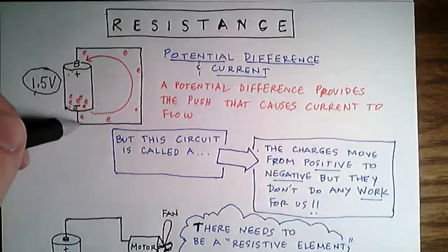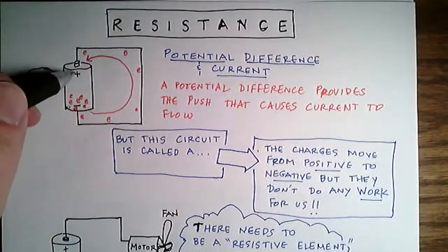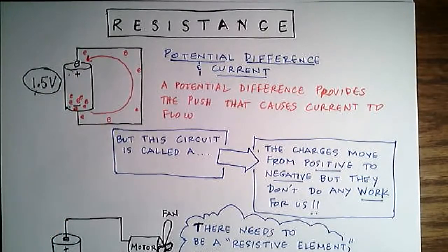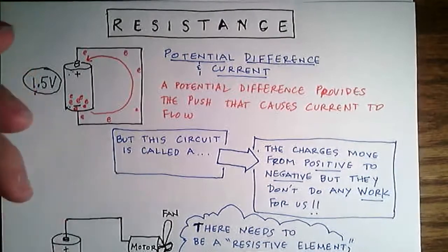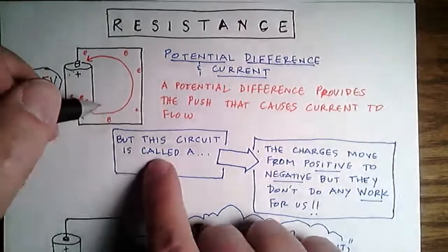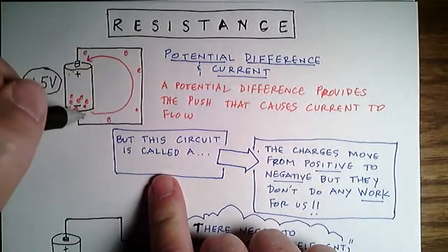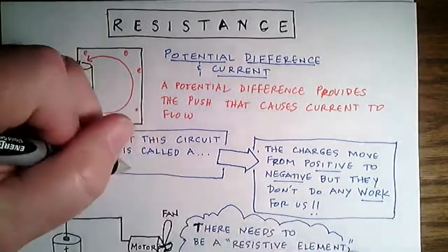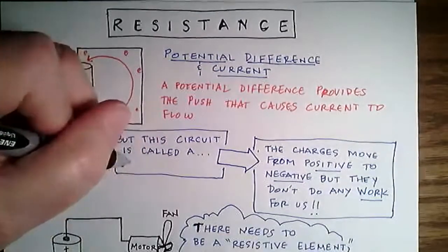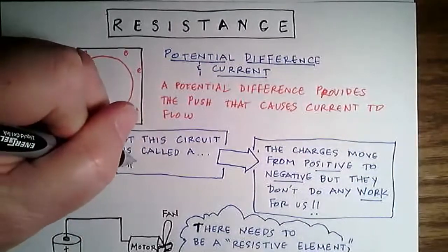They can run so quickly that this wire would heat up and maybe even melt the plastic that's around it. Or if it's in close contact, if this was in your walls, for instance, it could cause a fire. So what we have here, when we have no resistance, nothing really slowing this down, we would call this a short. I meant to do this in red.